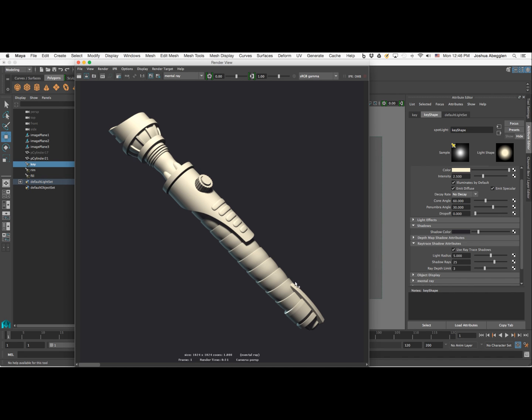All right, here we go. I've played around with the settings just a little bit more to customize it to get a better effect. I increased the intensity of my key light to 2.5. I also made it a little warmer still. I went to my rim light and I made that a little bit more opaque as far as the application of color goes. It has a stronger blue tint. All right, left the fill settings alone, with the intensity set to 0.1.